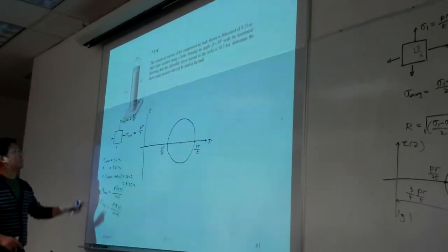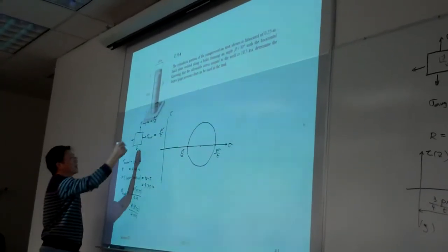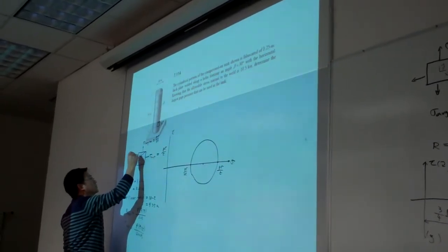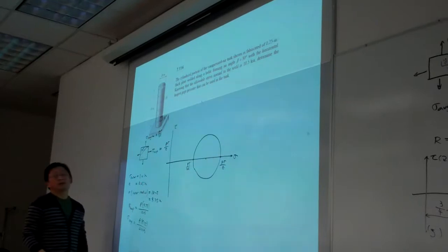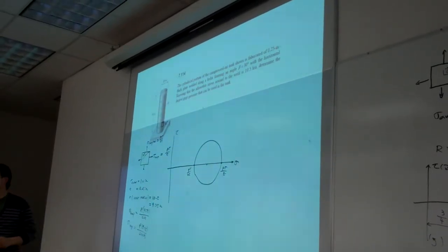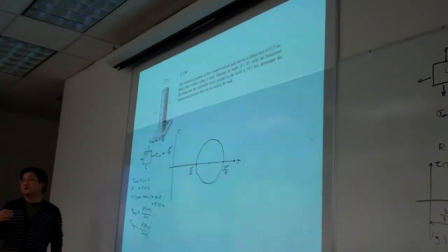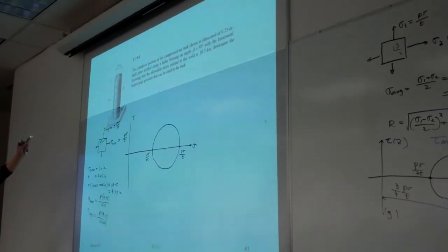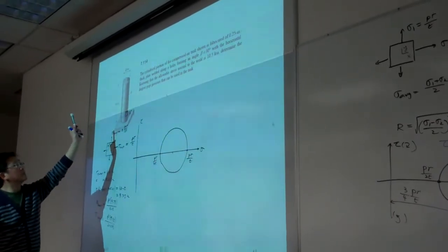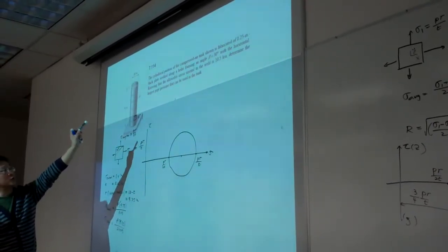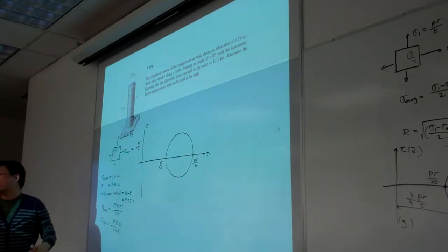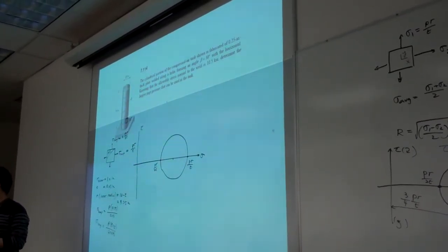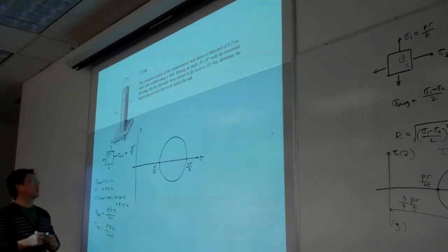Now, in this case, you can see right now the welding is in this orientation. This is 30 degrees. The problem statement says the normal stress to the welding surface has a constraint. You read the certain lines: the allowable stress normal to the welding. Normal to the welding means that the allowable stress is constrained to the normal stress. Okay, so that means here,